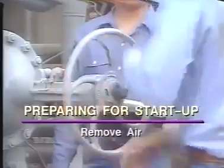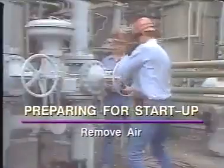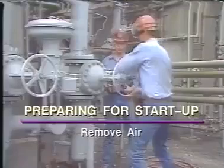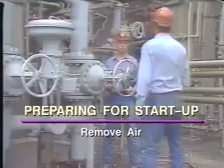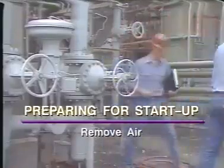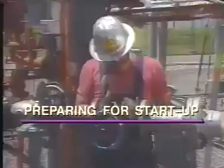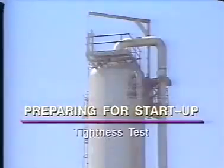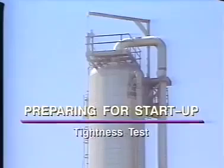removed. This can be done by adding an inert gas like nitrogen or steam to the tower. An oxygen analyzer is then used to verify that no air remains in the system. All blinds installed during the shutdown process must be removed prior to startup. Before the tower is brought back on stream, it is necessary to perform a tightness test to make sure there are no leaks in the column or in the connecting equipment.